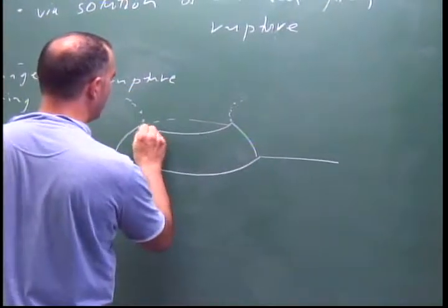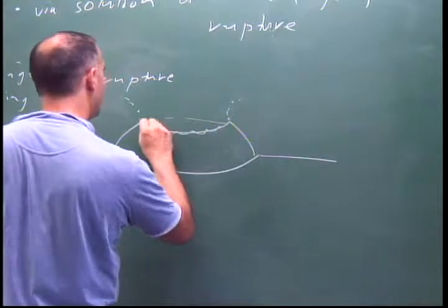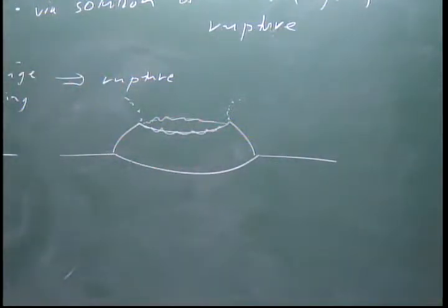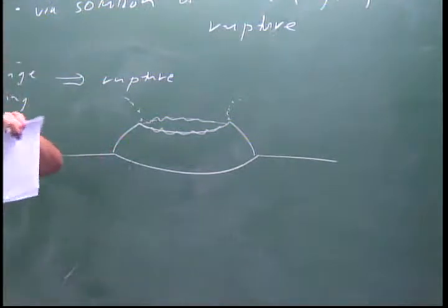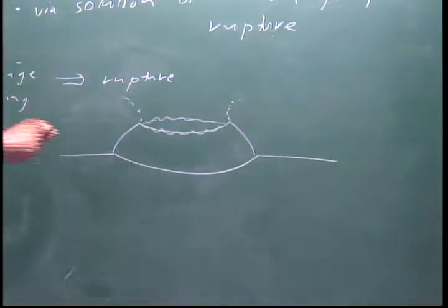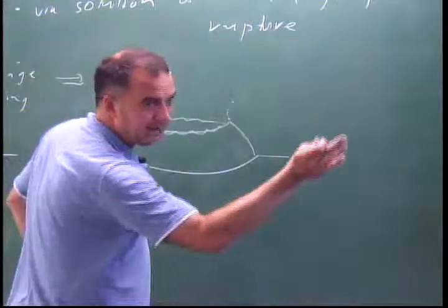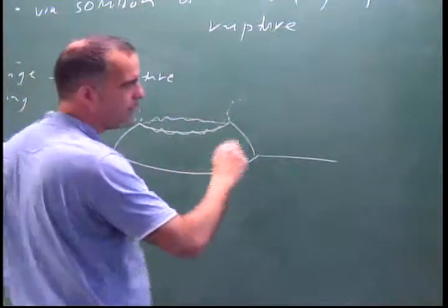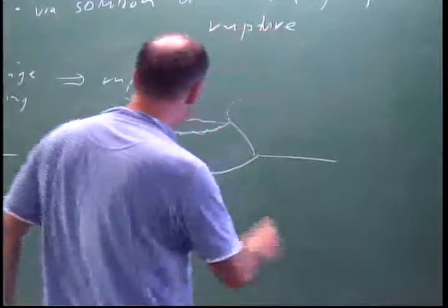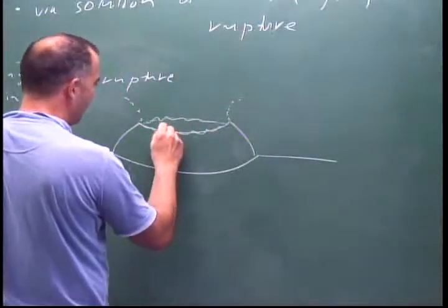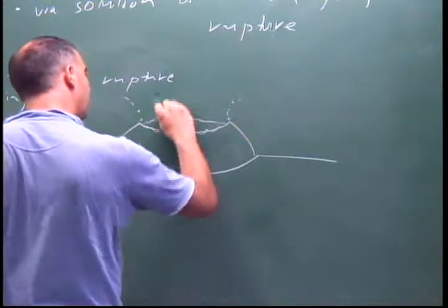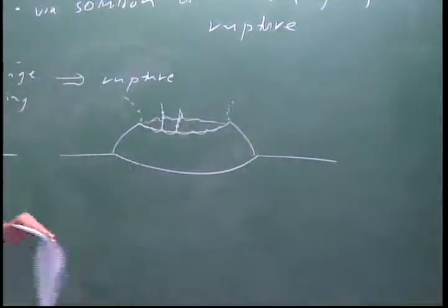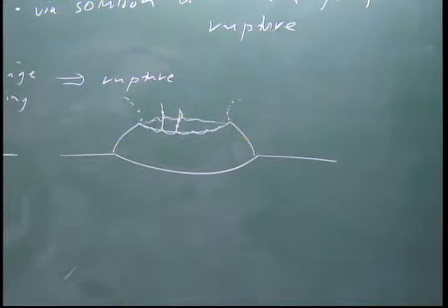so this thing is going to go unstable, right, as it retracts, because the rim has fluctuations due to the Rayleigh-Plateau, and also as this thing's being pulled back, there's a centripetal force which is throwing fluid outwards, so which is why you get the drops being flung outwards. You can get tendrils here, for example, and these then pinch off themselves due to Rayleigh-Plateau. So you basically have this cascade of droplet formation.